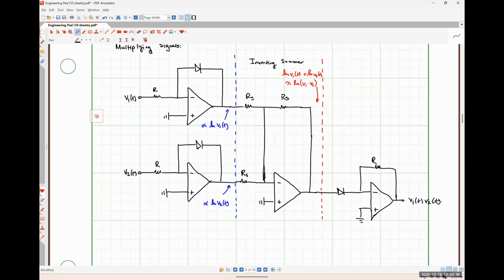And that's the order that you put them in when you cascade them together. That's analog signal processing design. Literally just, well, I need to do some sort of addition, so I'm going to have a summing amplifier. And I need to add some sort of DC bias, so I could do that with a summing amplifier. I could also do that with a differencing amplifier by adding a negative signal in.